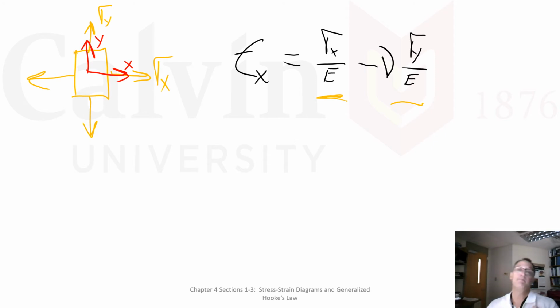Well, you can, following the principle of superposition, but the principle of superposition has two key assumptions in it. One is that these events are independent of each other. Are they independent? Well, that's tough, but that's the assumption we've got to make. And the other one is that these events are linear. We already looked very briefly at this material property curve, the stress-strain curve, and we're saying it has to be linear in order to add it together.